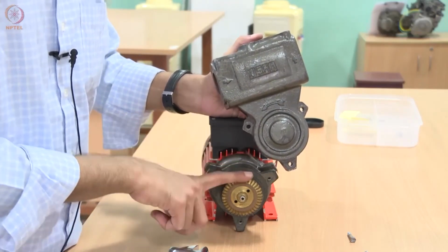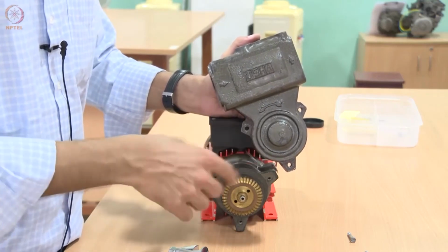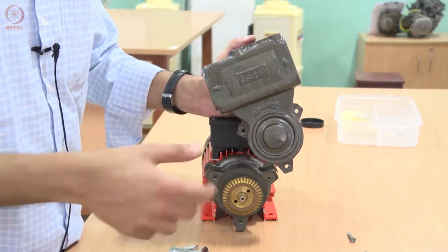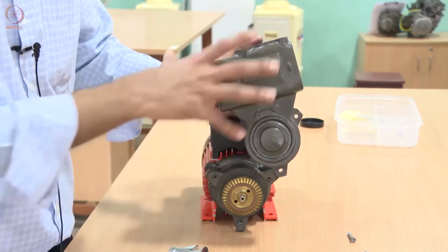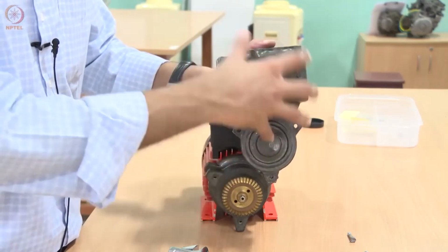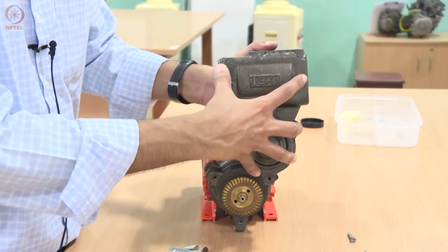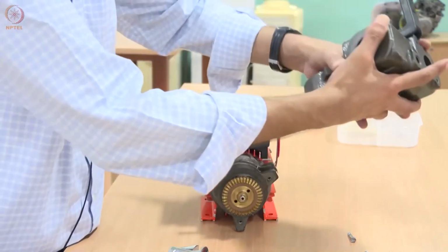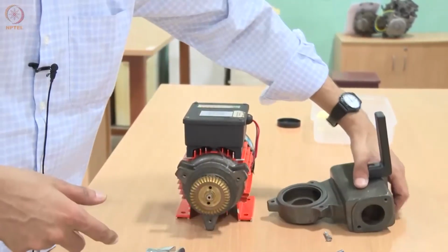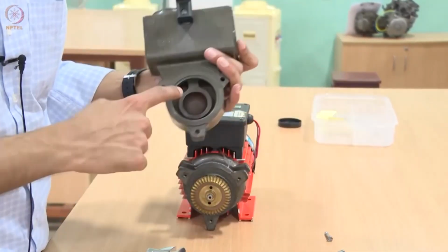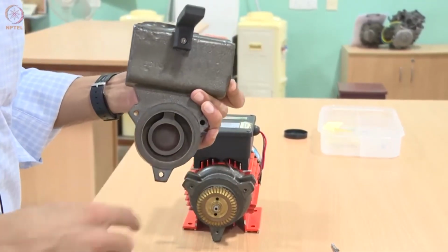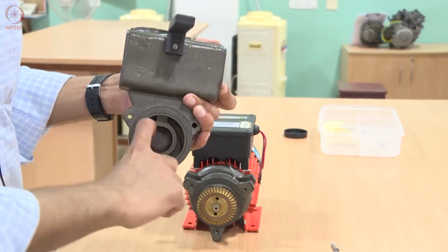In the case of a centrifugal pump, depending on the volume of the suction line, you may have to fill something like 15-20 liters of water, depending on how long it is. In this case, because of the design, you only need to fill a very little quantity of water, and the pump primes itself. This also doesn't have what is known as a volute casing. You can see the casing is more or less uniform throughout. In a volute casing, you will have a gradually expanding outlet.